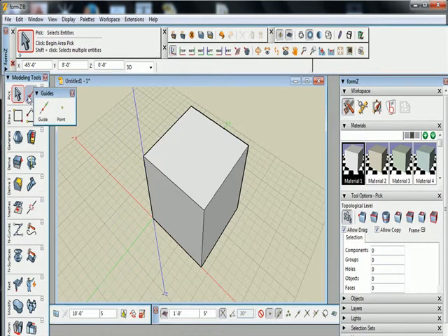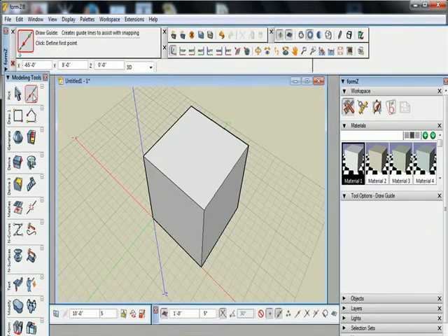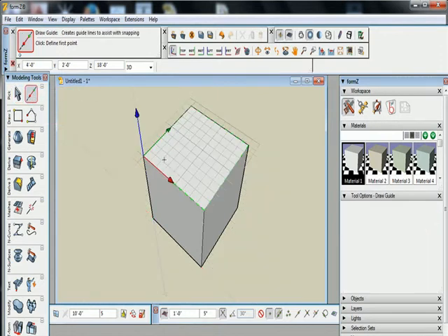Okay, so select the guide tool, and then notice that if you hover the cursor over a plane, a reference plane gets attached. If you hit F5, it's going to lock that reference plane. If you hit F5 again, it's going to release. What we want to do is select the top plane. So you can hover your cursor over and hit the F5 key, or just be careful about it when you're working, and then